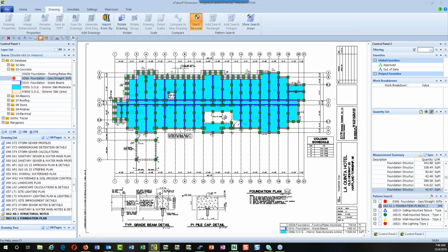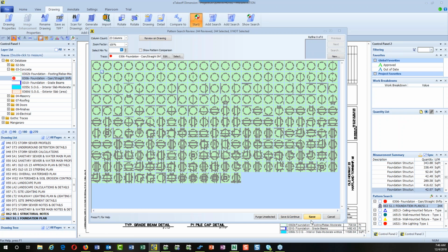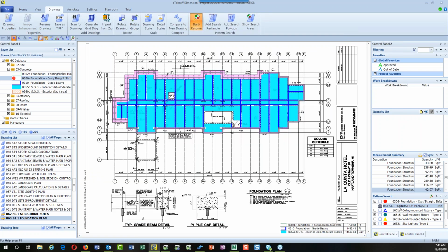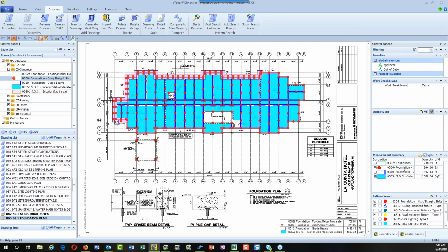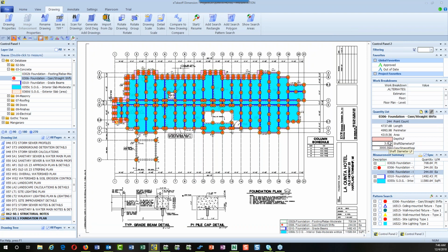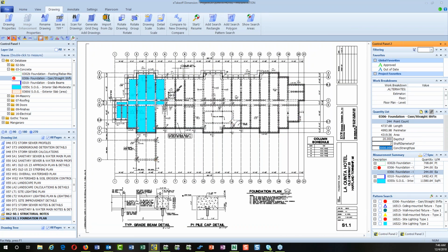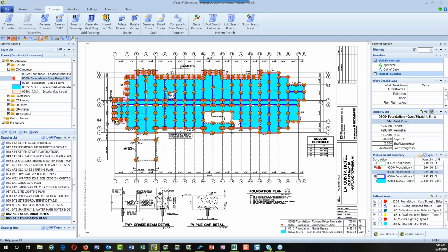So I'm going to go ahead and accept that. So I'll go back here to see these, and I'll go ahead and accept that. It'll add it to my line estimate. So I added 244 right here. I'm going to click on this so I can fill in the spec information, and specs say it's an average of 20 feet deep. They're 2 feet in diameter, and it's 3,500 PSI concrete. So I'll just put that in here,